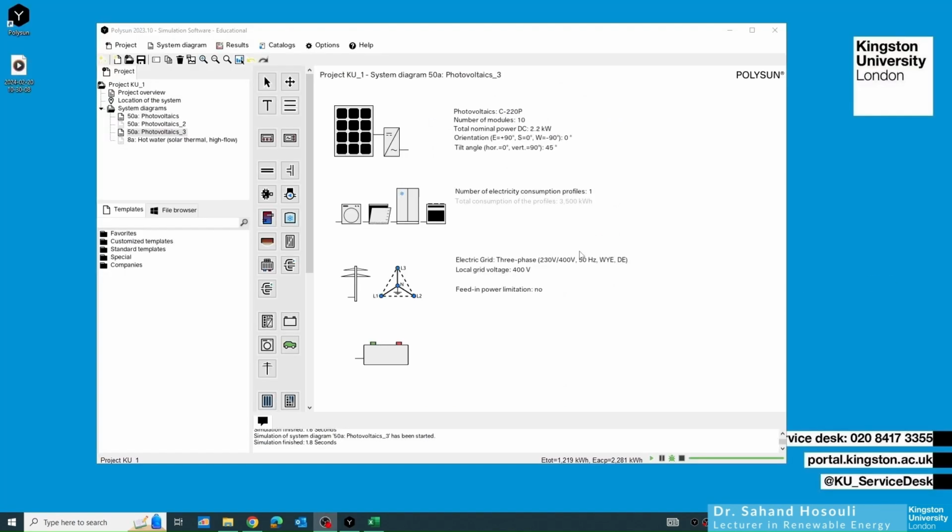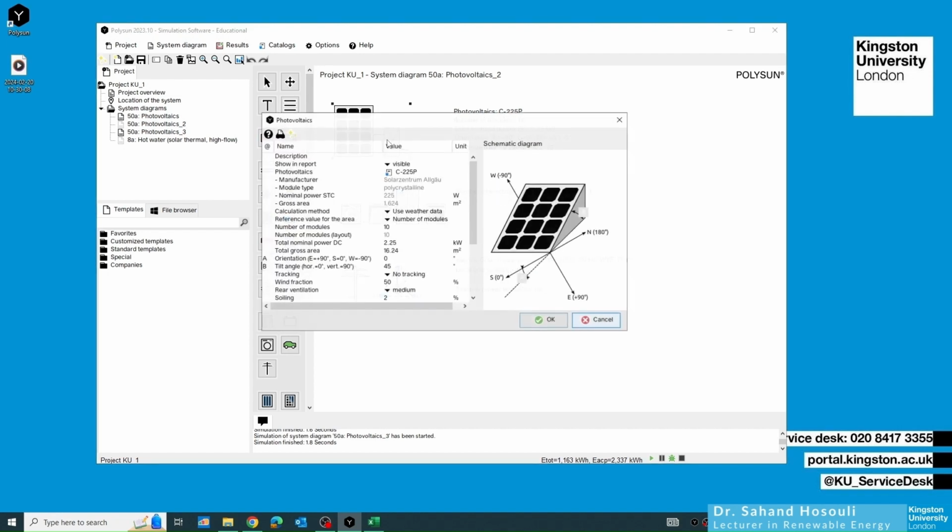What we have done so far was basically focused on the information we got from the wizard section here. Considering a case that might be imposed by our partner or by a user, that I need a specific kind of inverter, because as you remember, the wizard automatically selects the inverter for us in our system. So let's go to this photovoltaics 2, and as I said, let's consider that a consumer imposes us to use a specific kind of inverter.